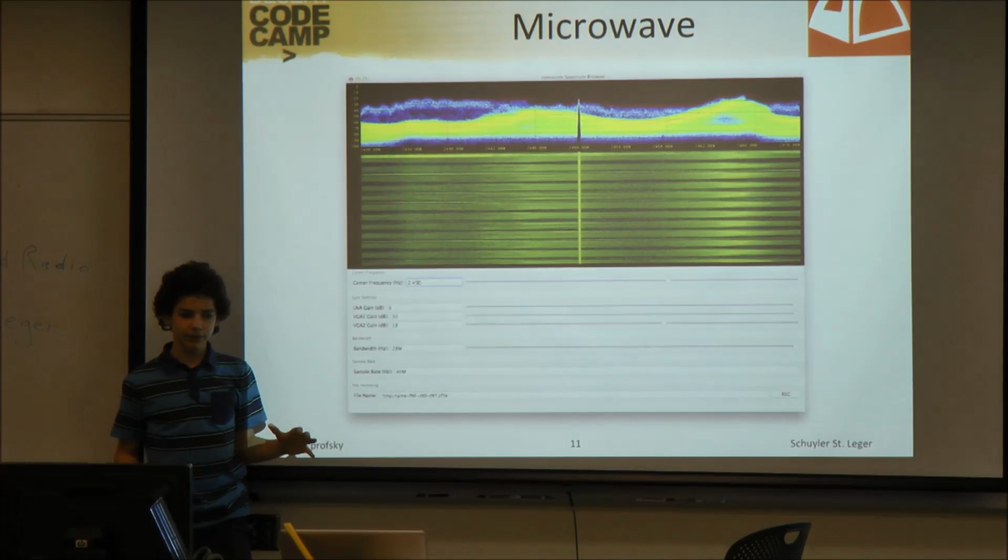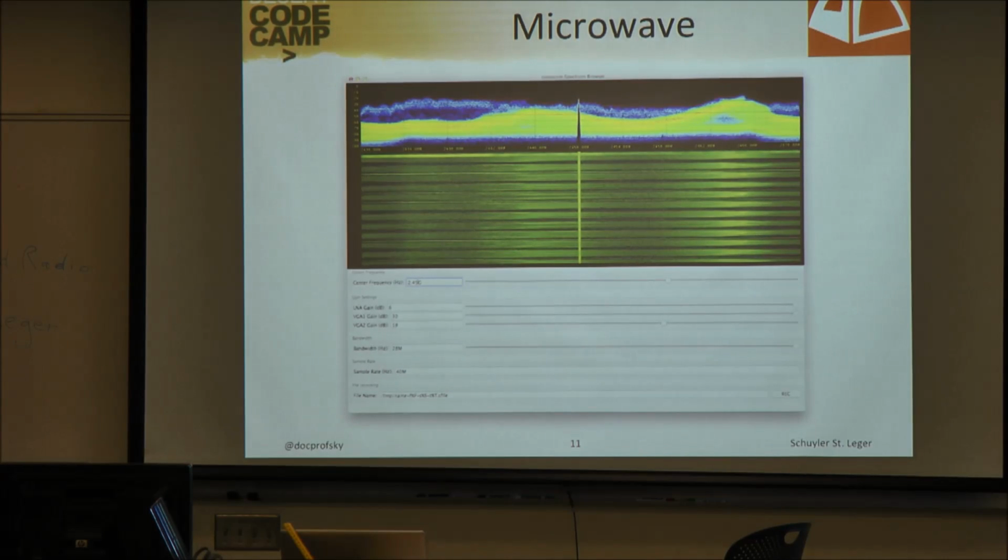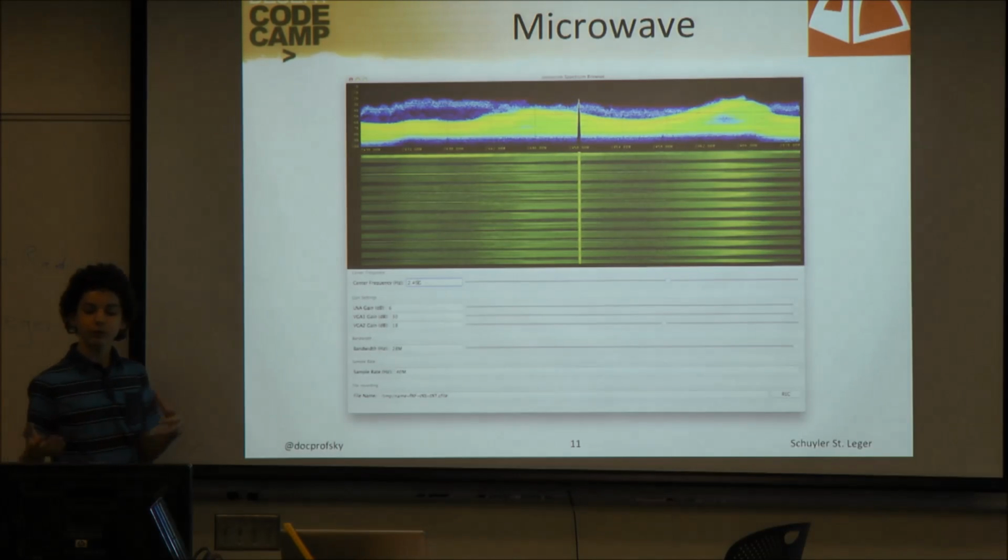There are certain radio designs where, if here's your frequency and here's your amplitude, and your signal is up here, it'll go through the mixer, and your signal will go in, and then you'll have a local oscillator. The signal out here will have a peak somewhere, typically centered around or near 0 hertz. There's what's called low IF, or low intermediate frequency, and that means they'll put it at around maybe 10 to 100 kilohertz. When you do that, you typically get rid of the DC offset. But it also means your ADC needs to be faster. So it's really just a trade-off of what you want.